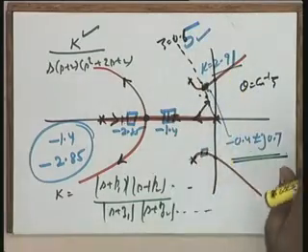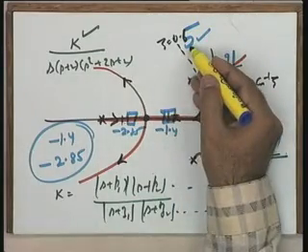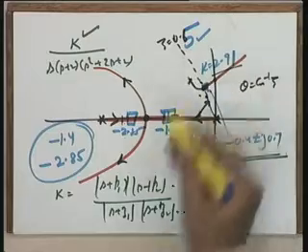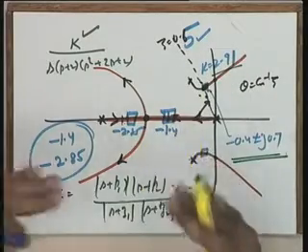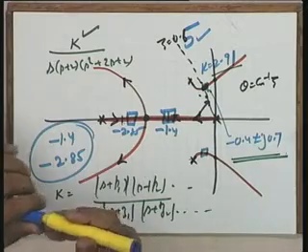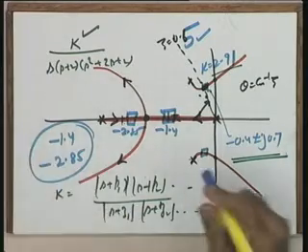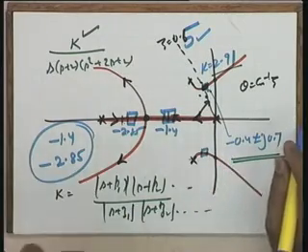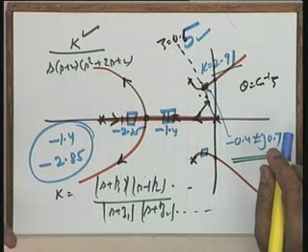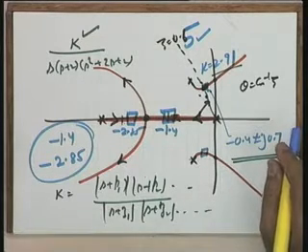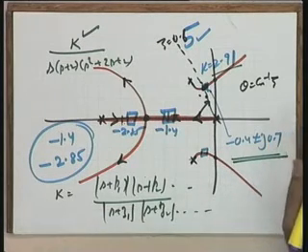So I make a statement that the peak overshoot corresponding to zeta equal to 0.5 may not come up because of the presence of these nearby poles, and hence it will be clearly shown by the simulation exercise only. And you have to enter into the design cycle suitably so that the complete acceptance of the response of the system is guaranteed as far as user requirements are concerned.